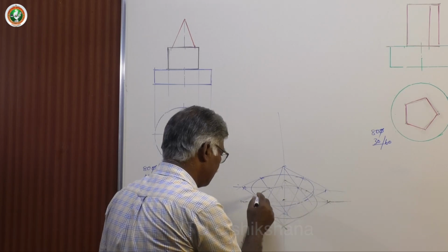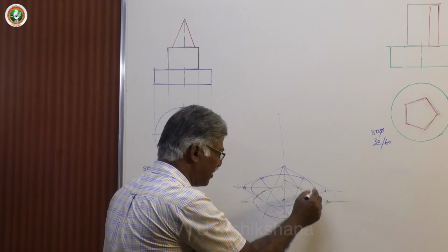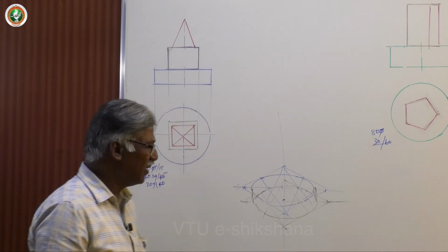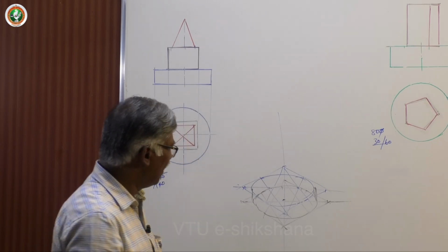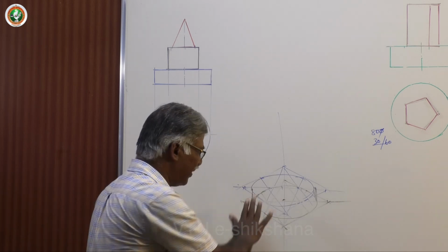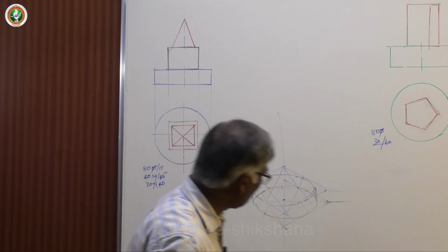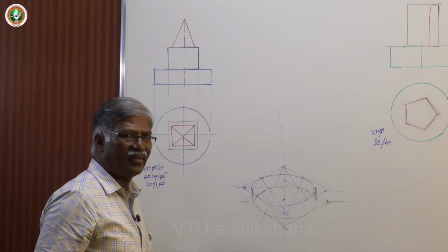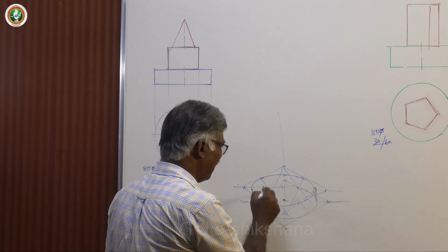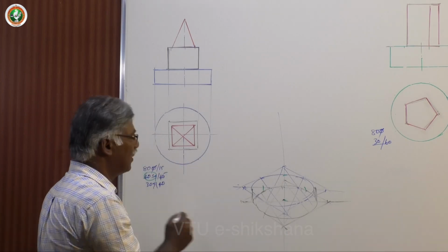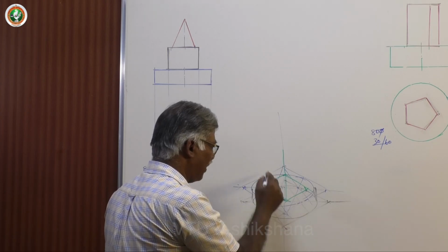thin line. Now join these two figures with vertical lines, tangents. Tangents must be vertical only. Now for doing manually, particularly if you are working with pencil, touch lightly with the rubber and then make it a little bit light. Then start working on the square shape. Again plus mark, already the plus mark is available. Then 20, 20, 20, 20, because 40 is the size. Then draw the base. Then go up by height 45.